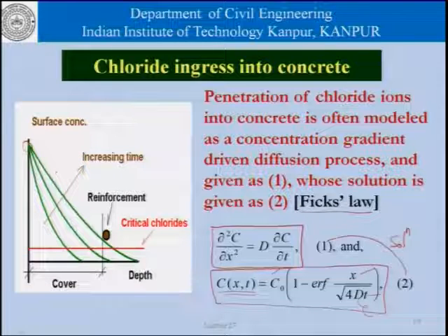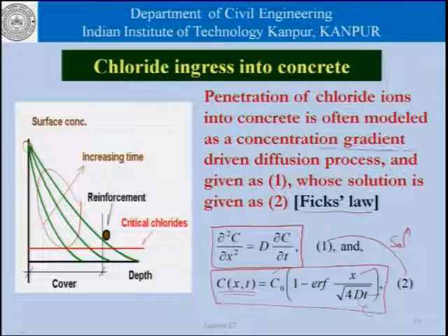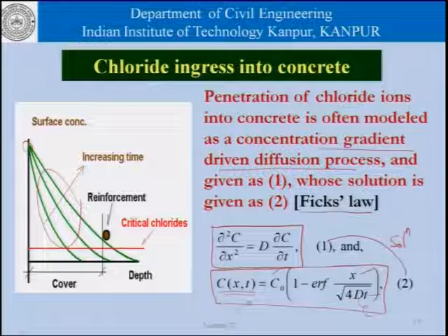This phenomenon, if it is represented as a concentration gradient driven diffusion process, these curves can be represented through this kind of an equation. It stands to an argument, we can discuss it, whether or not chloride penetration in concrete is indeed a diffusion process, or it is a concentration gradient diffusion process alone.